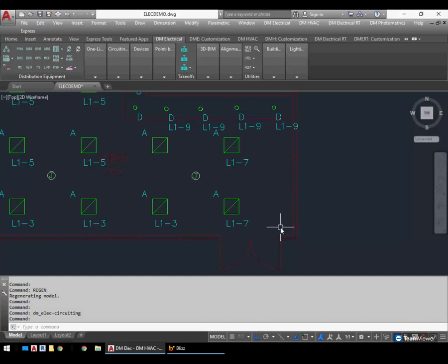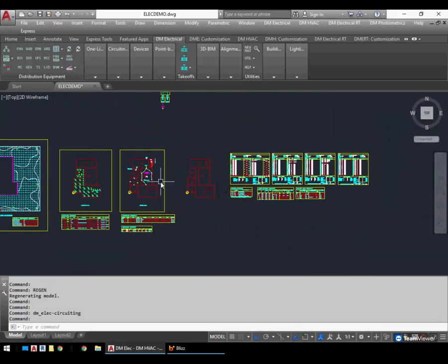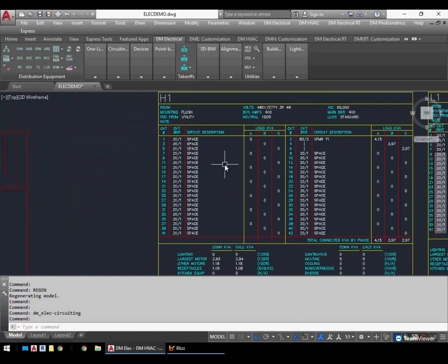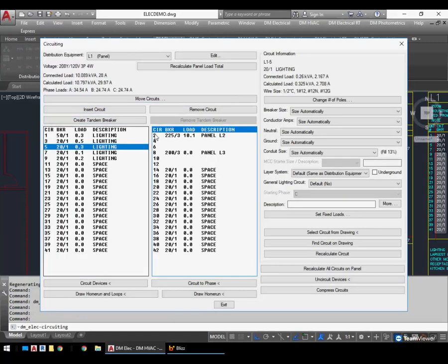Here's a question. How do you wrap the text in the description box so it doesn't run on the panel schedule? So that's a good question. You've got the longer circuit description, and obviously you want your panel schedule to look nice. Our panel schedules do wrap the text, and our newer ones, if you're using any of the ones that are the yellow and red color scheme, have that built in. If you have older panel schedules or ones that you've customized, it might not have it. So you might have to make some changes. So first of all, just how that functionality works.